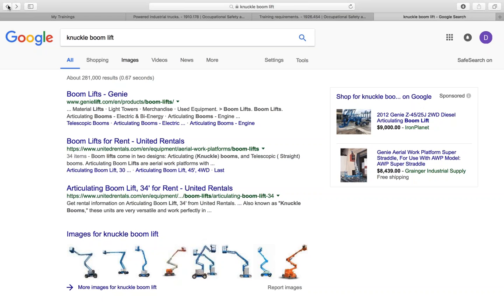Also, the following tasks have to be performed before operating that lift. What are we going to do? We have to carefully read and fully understand the operating procedures in the operator's manual, and any warnings, instructions or decals. In addition, we have to check for obstacles around the work platform, anything in the path of travel, like holes, drop-offs, debris, ditches, or soft fill. We're looking for anything where the weight of that vehicle while we're operating it may be affected by substandard ground conditions, okay?